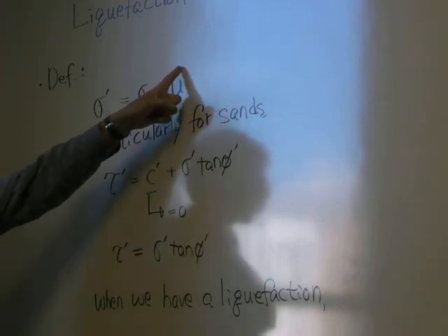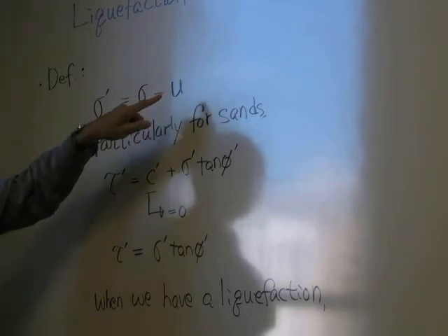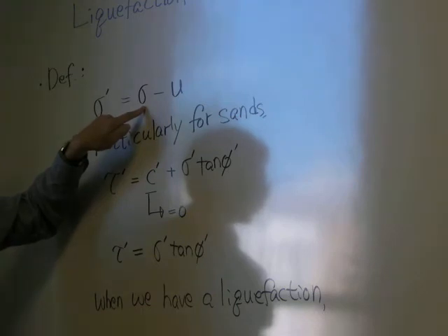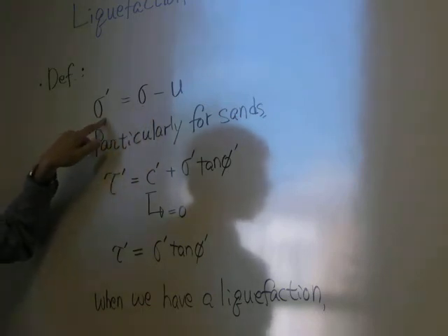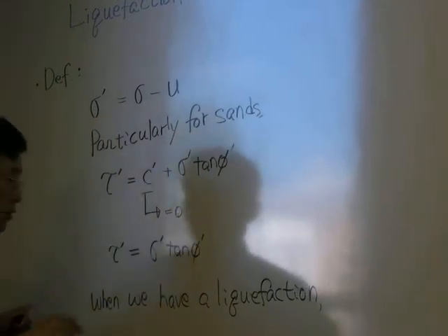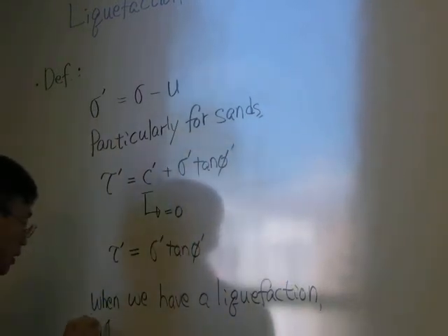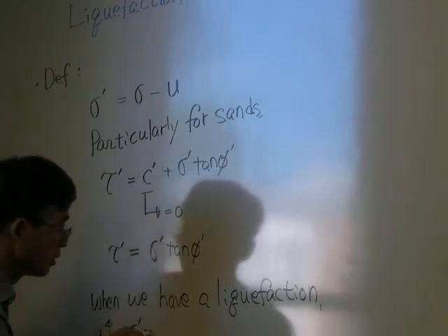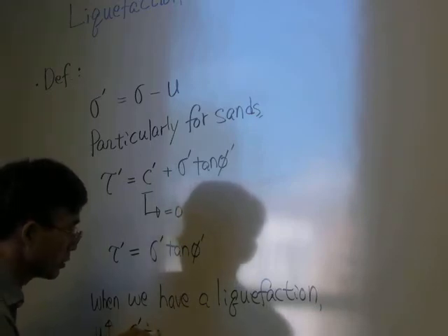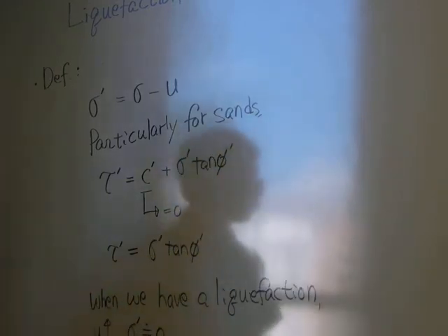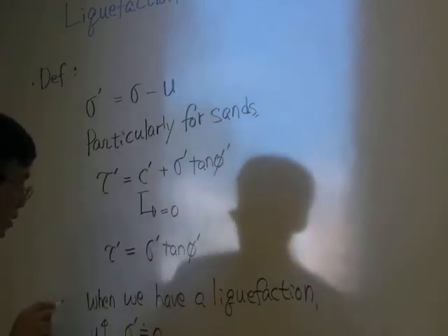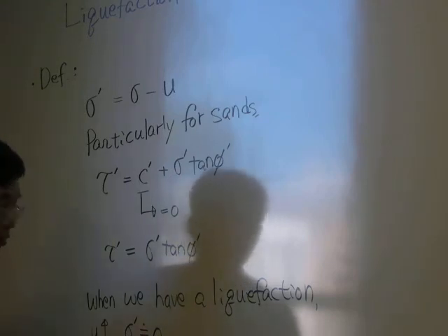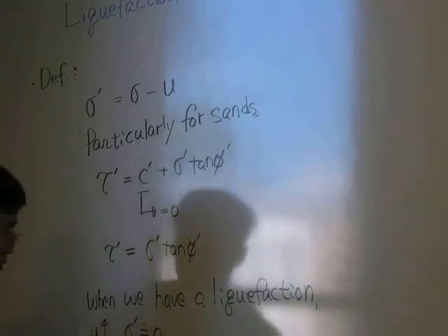Then the magnitude of this pore pressure will be about the same as this guy, total stress. Then what happens to the effective stress? 0. Pore pressure will rise up and effective stress will be approximately the same as 0. That means what happened to our shear strength? 0. 0 again.